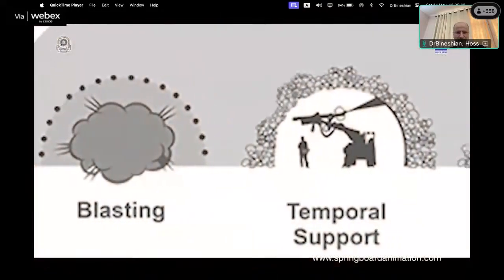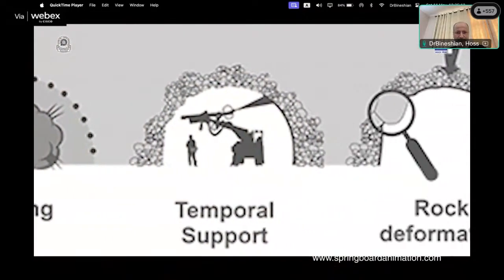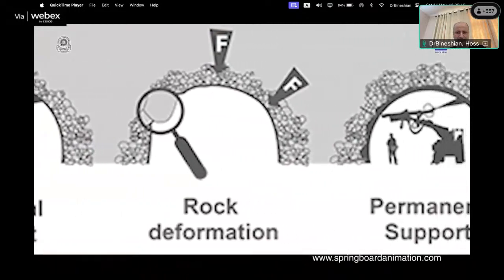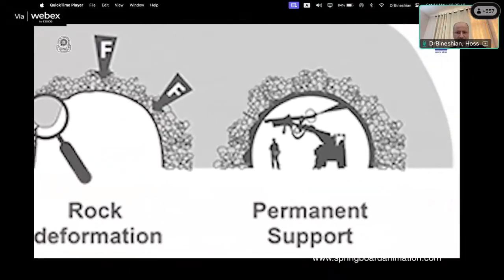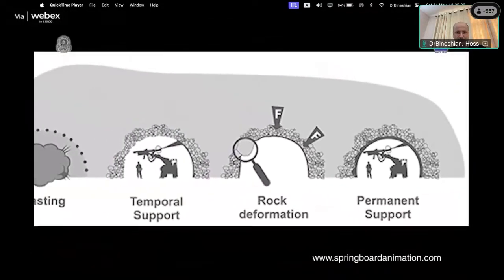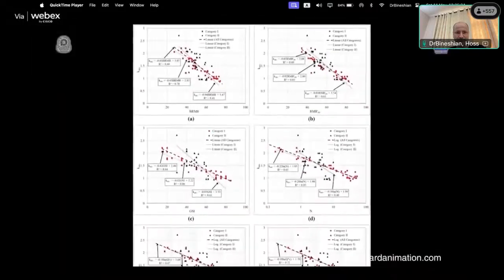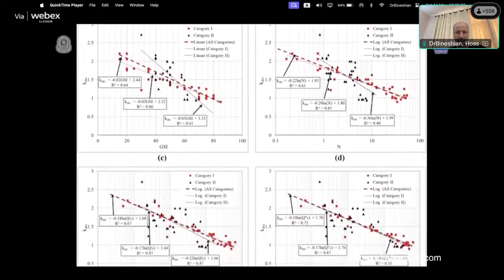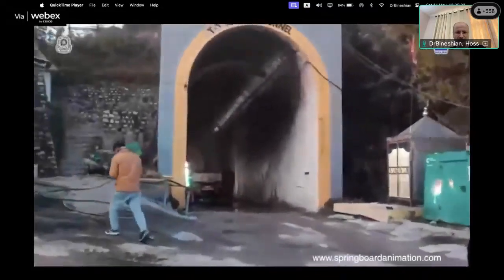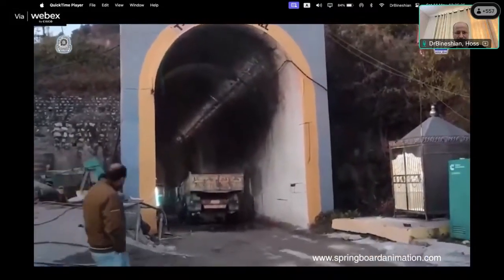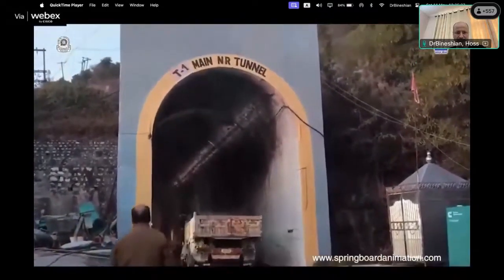This was due to the adoption of inapplicable design and methodologies because of misinterpretation of the mechanical behavior of the ground by designers, employment of inappropriate tunneling methods including conventional and NATM, use of inapplicable rock mass classifications including Q and RMR, and application of unsuitable materials and machineries, which resulted in a huge loss of time, resources, and machineries.